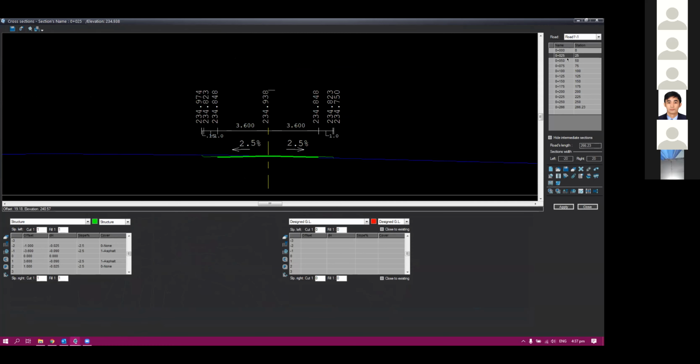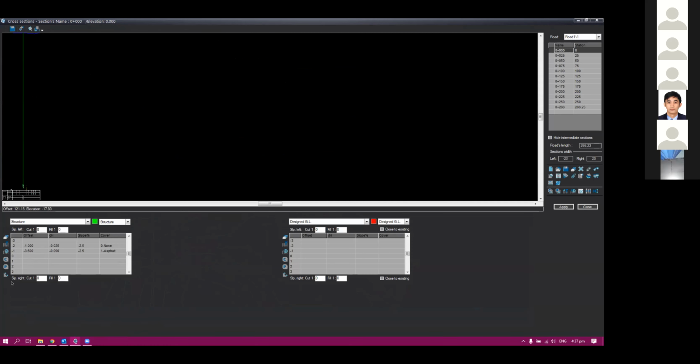I started the cross section at station 25 because there's an error in my station 0. You didn't do anything. Okay. When I first applied this. No, I understand, it's very good. Exactly. Look, guys, this is exactly what I want to see. I want to see problems and I want to show you how to fix them because these are common. This is real life. Let's see the error. The system says there is no vertical alignment definition in this section, meaning in the beginning of the road, you didn't design a profile.